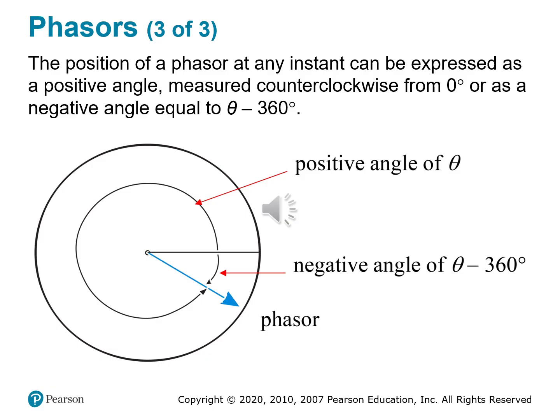This is powerful because it allows phasors to represent phase shifts precisely. It translates rotational motion into linear waveforms. It can be graphed and compared when signals are out of phase. So when we say two phasors are 90 degrees apart, we now know what that means, that one has rotated farther than the other, and that rotational difference shows up as a waveform shift in time.